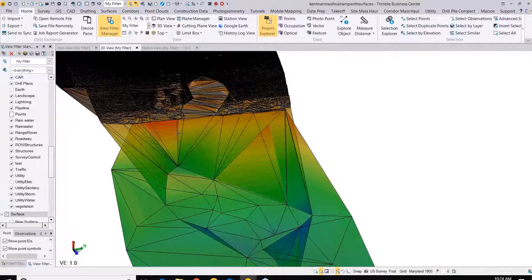Yeah, we'll see if he follows up. Another one came in from Jesus. Were the shots OPUS corrected or with a local base? Because he's noticing that those were control quality. Yes, those were set with the VRS network, the KeyNet base, that runs from Virginia to Maine. That's through Keystone. I actually went to Corbin this year for the Sino America games, and that was set to the NGS standards, where you take 3 shots at a third each for 3 minutes. So there's 9 minutes on each of those.